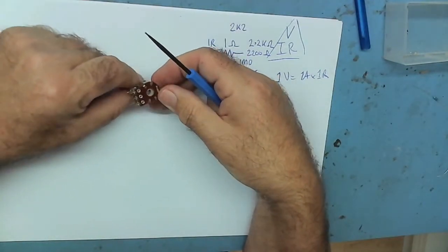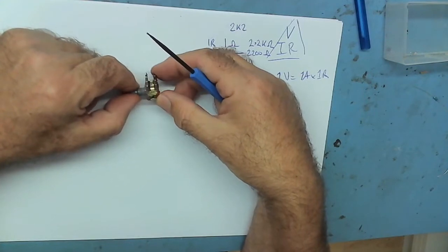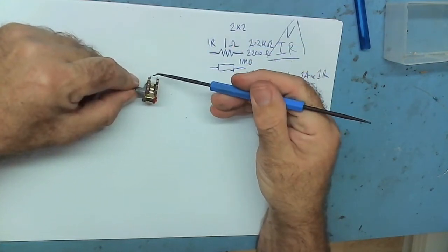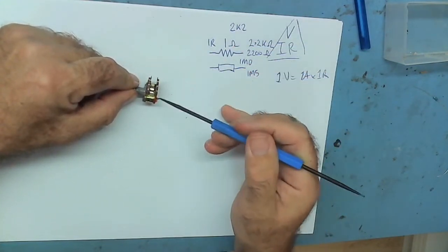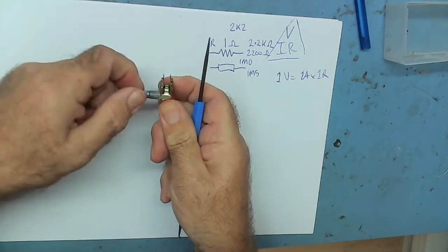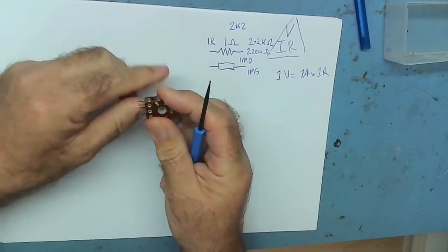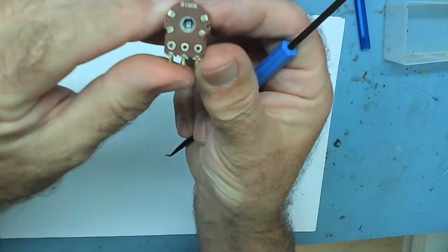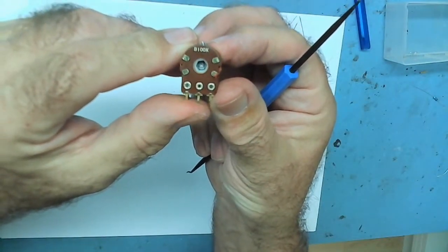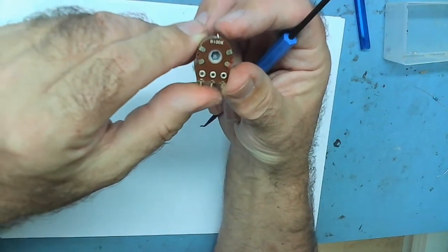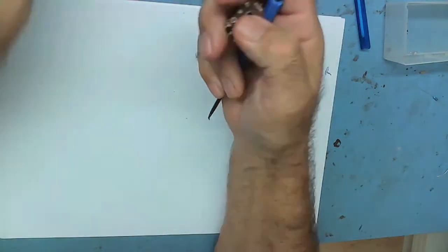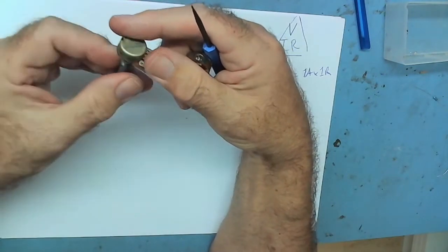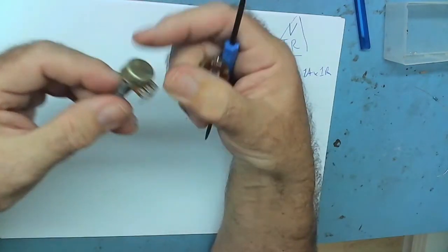There's another one. That's another variable resistor. If you see this, it's two gangs. So in here, there's two variable resistors controlled by the same shaft, yeah? B100k, 100,000 ohms. The B won't be a tolerance on this. I'll tell you what the B is. And this one was B as well, 100k B.